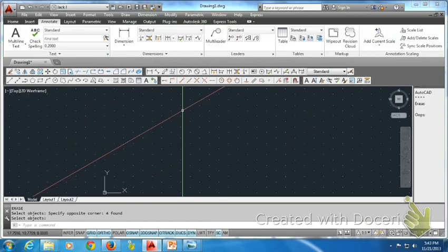A cavalier on page 673. Remember, the front view is going to be full scale, regular front view, and then the receding lines on a cavalier are also full scale. The difference between a cabinet and a cavalier is that a cabinet is half size.